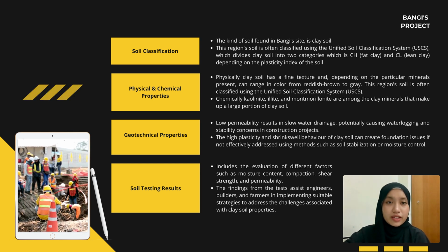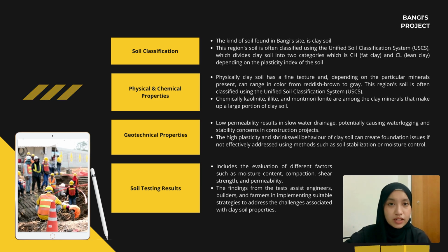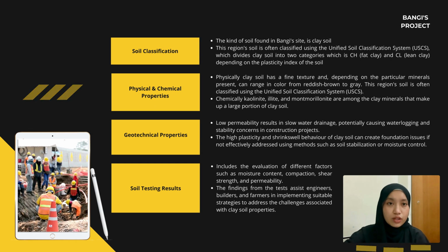Next, for its geotechnical properties, low permeability results in slow water drainage, potentially causing water clogging and stability concerns in construction projects. The high plasticity and shrink-swell behavior of clay soil can create corrosion issues if not effectively addressed using methods such as soil stabilization or moisture control.